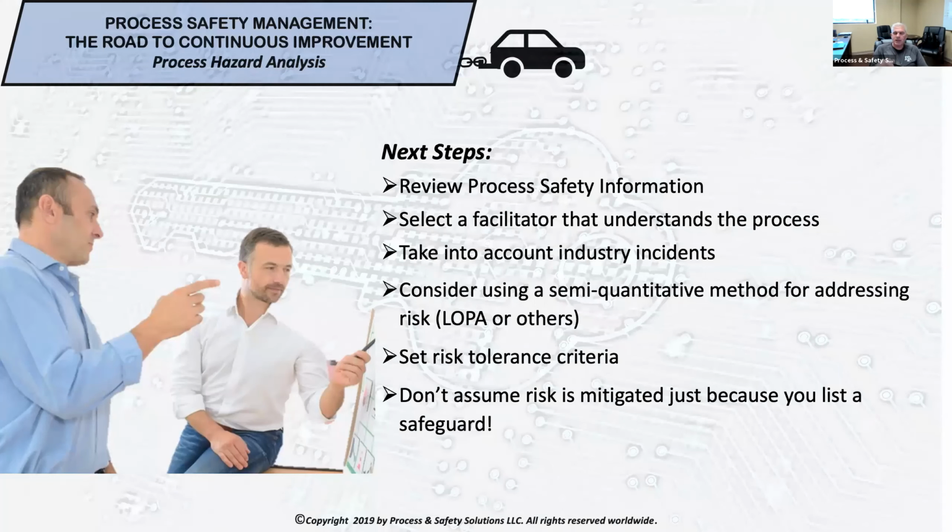Don't assume risk is mitigated just because you have a list of safeguards. And this is what I see quite often, is people will tend to list a lot of safeguards, but they really haven't mitigated the actual risks of the consequence that they've defined.